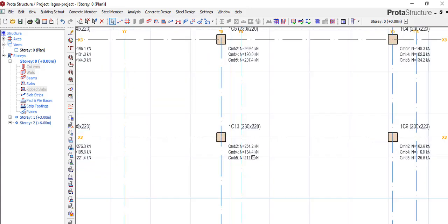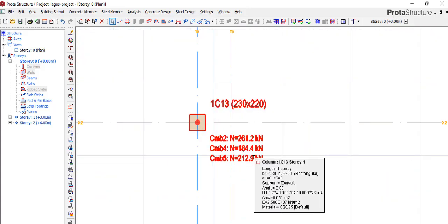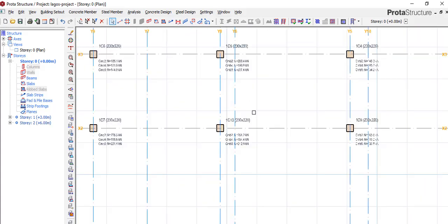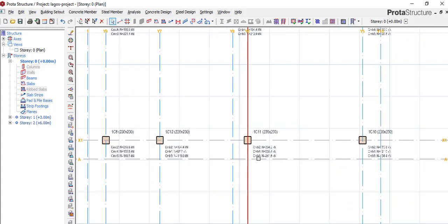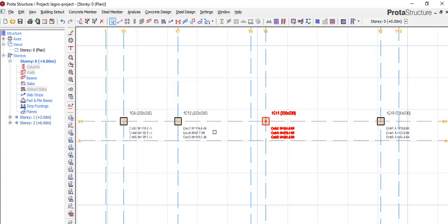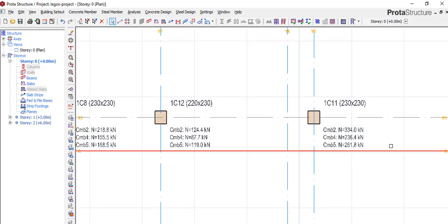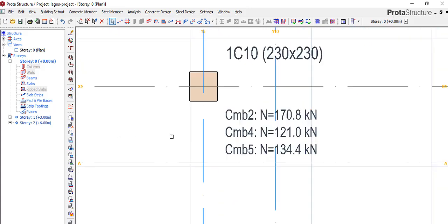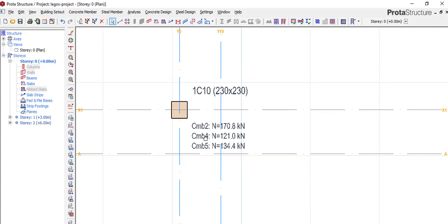So this, from our soil reports, the safe working load for the pile is 389, if I'm not mistaken. So they all fall under it. So okay, this is 3. Okay, still fall under it. All of them fell under it. So that is what we will do.